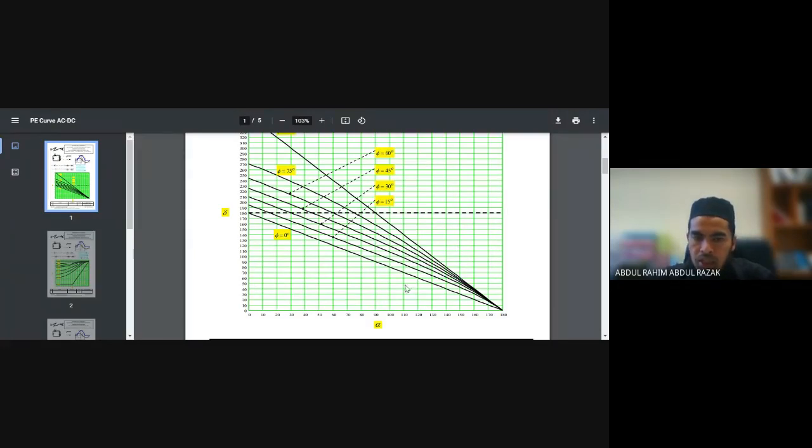That means what the expected range of extinction angle is, and then the information will be used further for determining the circuit devices, the size, the value or the setting of our input, or the limitation of our output range. So the PE curve can be used as a tool, and you can use calculation if you are confident with it, or you can use the PE curve because we just need to obtain the extinction angle. So this is the range of extinction angle